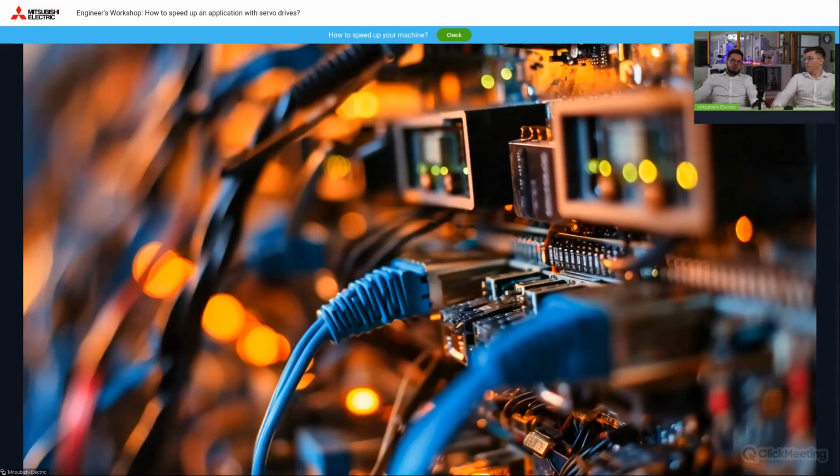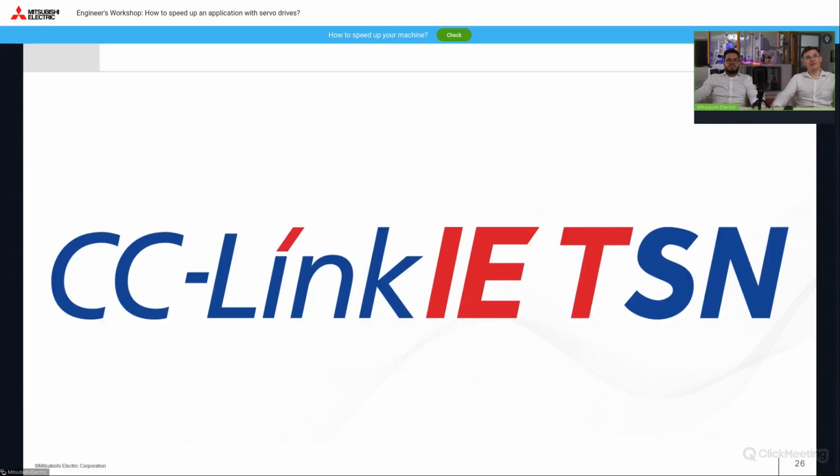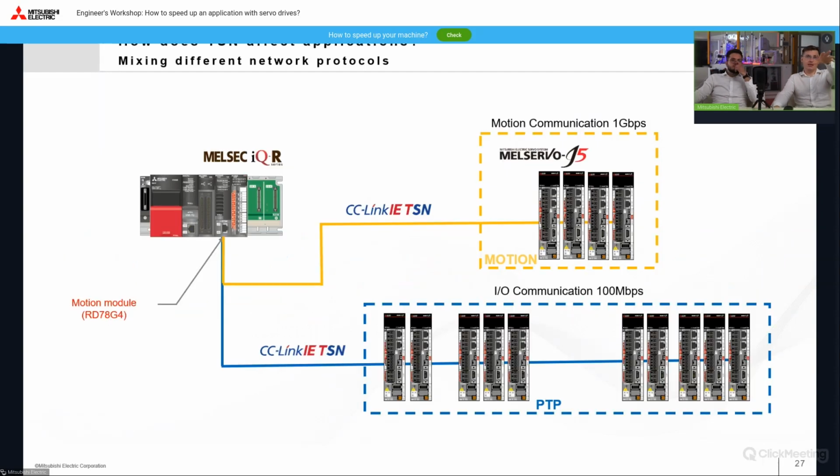A suitable motion controller is one thing. The question is also on which network it is connected. Well, for example, via our own CC-Link IE TSN network, which allows point-to-point and motion to be controlled within the same network, increasing flexibility of choice. Look at the network configuration. In the case of the 4-axis motion module, which means that we can control up to 4 axes in full synchronization, you can still add between 116 and even 348 such servo drives in the configuration.